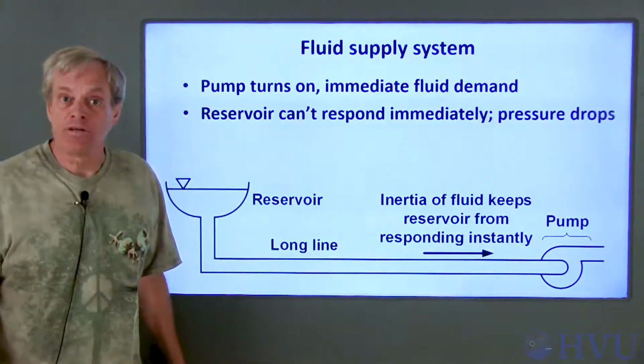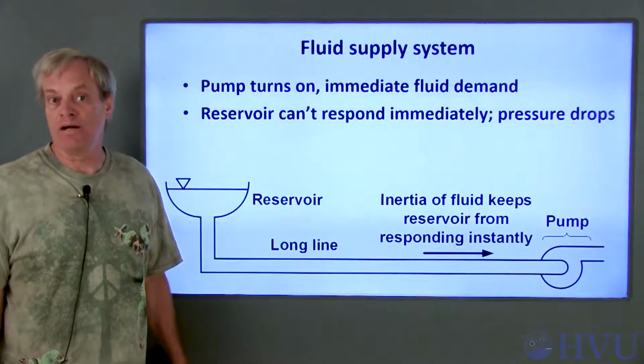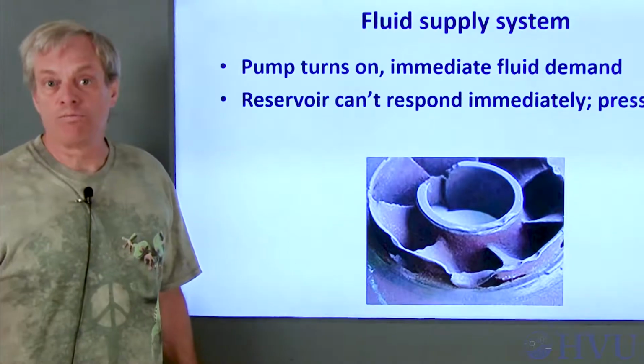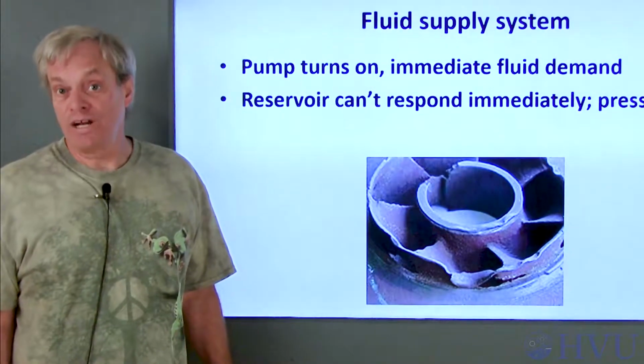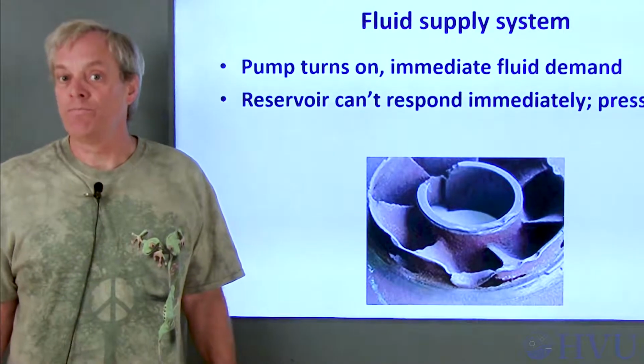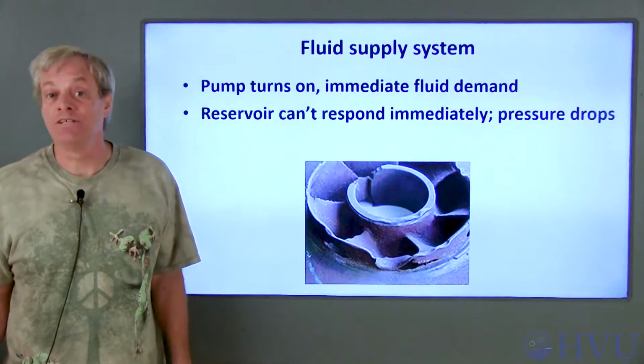If the pump inlet pressure drops too much, we get what is called cavitation in the pump. During cavitation, bubbles form on the pump impeller. When these bubbles collapse, they create very large pressures, which can pit and erode the pump impeller. This picture shows the result of cavitation, something we definitely want to avoid.